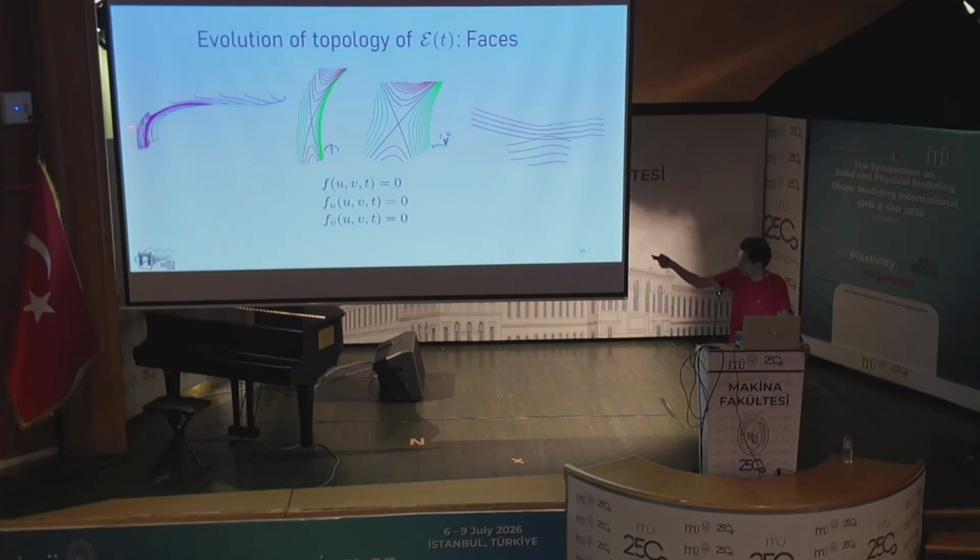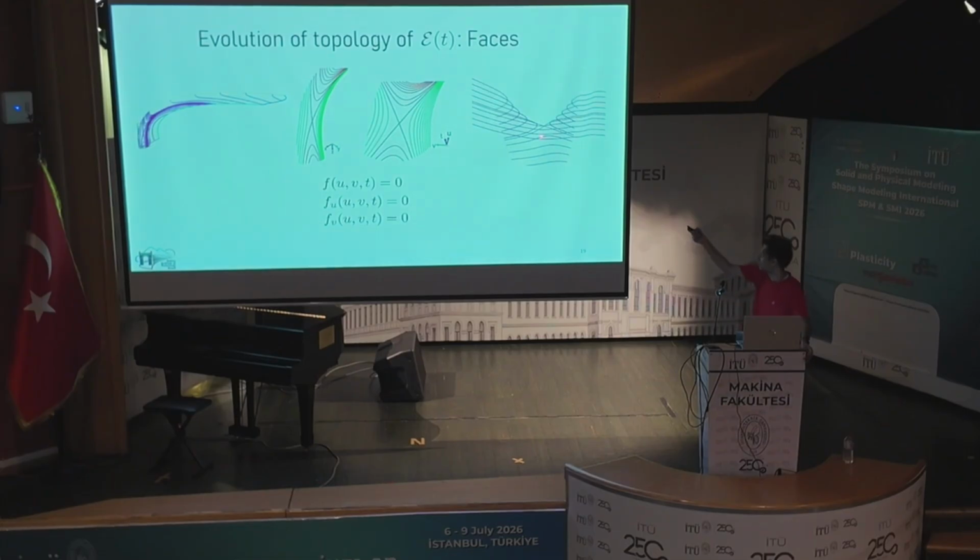So that portion where the topology changes is shown magnified over here in XYZ space, and the same is shown in the UVT space over here. And what is really happening is this. At each time, the curve of contact has two components, but initially those curves go this way, and later they go that way. So essentially, you have a saddle point. And in order to handle such cases, we first need to locate such points where this topology changes.